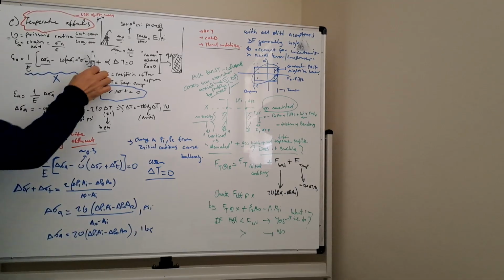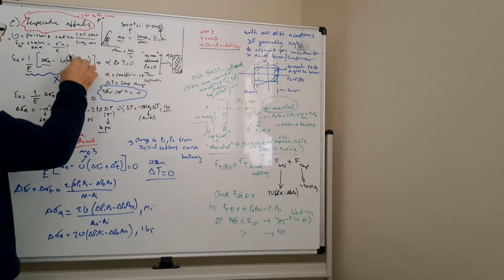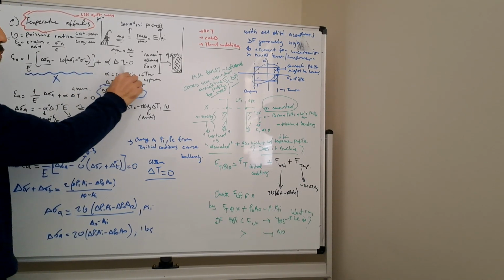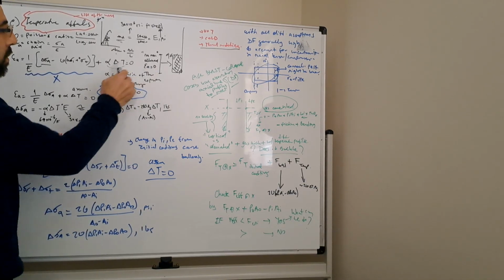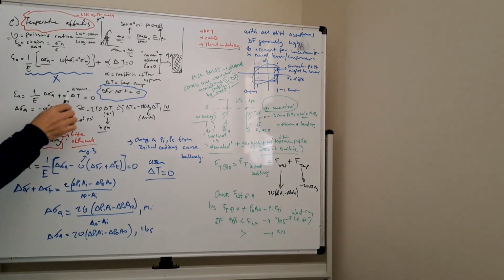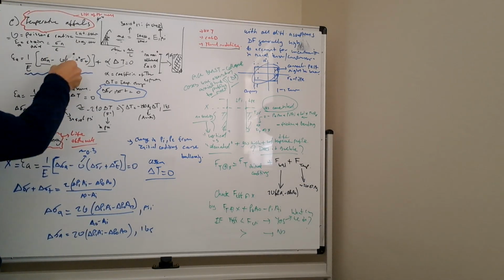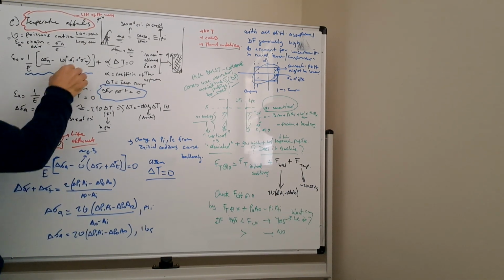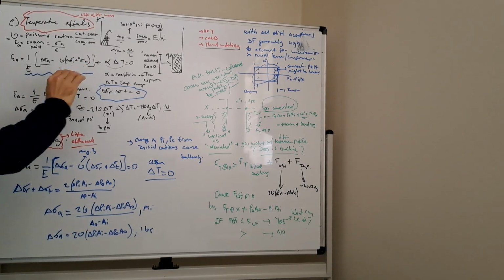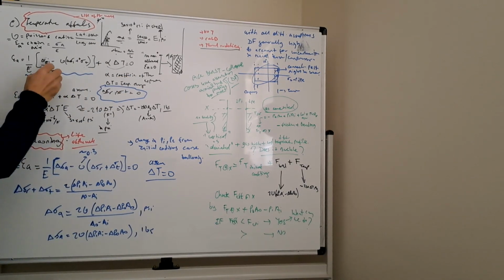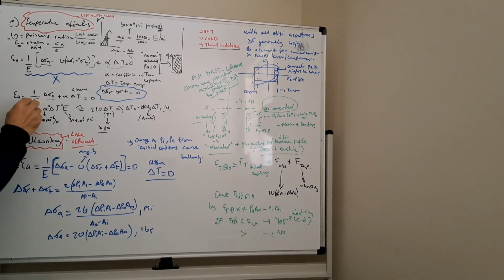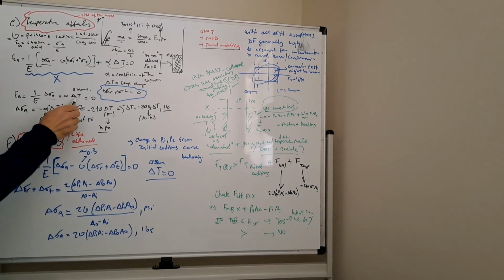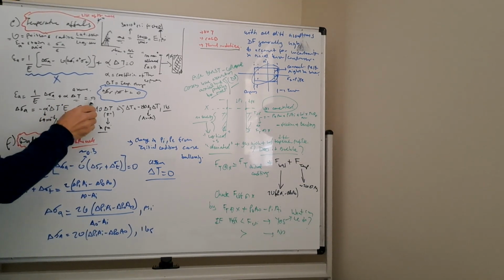So this side is the Hooke's law kind of a thing, stress over strain. However, this side is the temperature related movement, and we know that both of them together total will be 0. So here we are gonna ignore the radial and tangential forces because it's small, and let's call it no pressure changes. Then we have the change in axial stress divided by the Young's modulus plus the coefficient of thermal expansion times the change in the temperature is equal to 0.